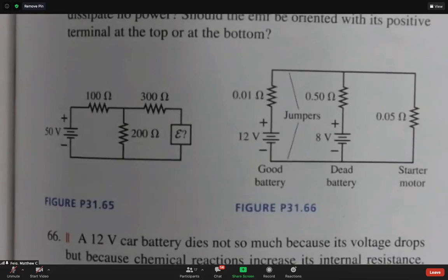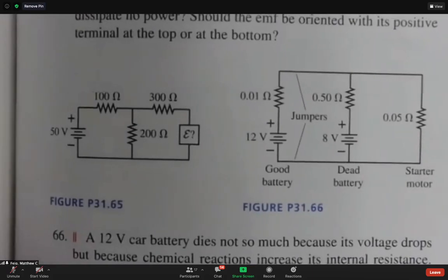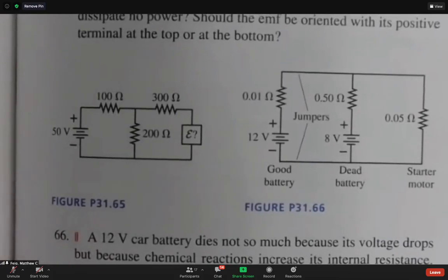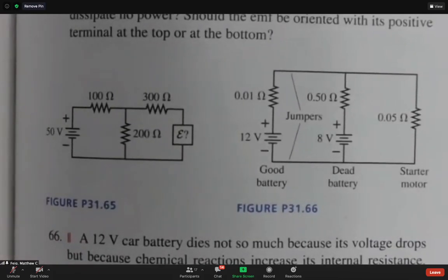So what's the current actually going to do? There's going to be no current on the middle branch, but there probably will be current somewhere. It's just zipping around the outside. Basically, if you did I1 for the left branch and I3 for the right branch, I1 would equal I3 at this particular setting because they differ by I2, and I2 is going to be 0.